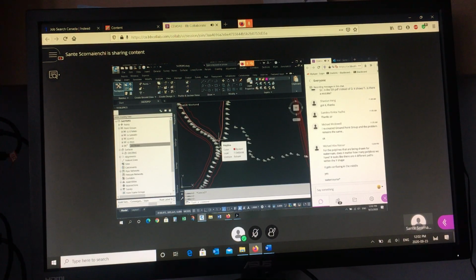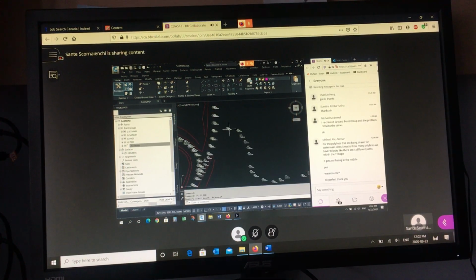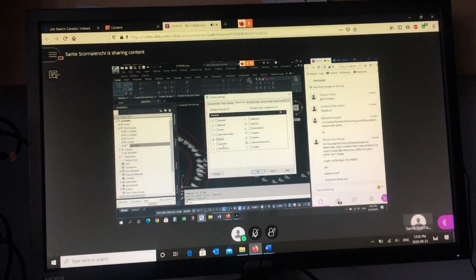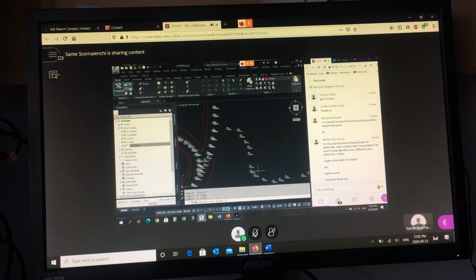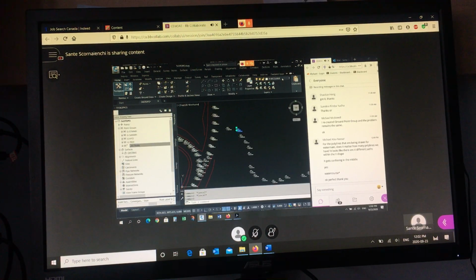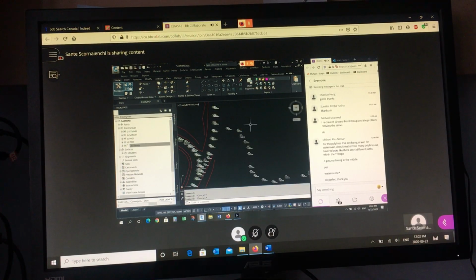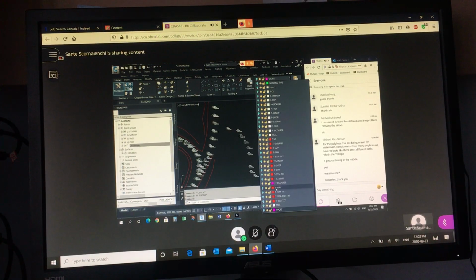Okay, so I can do this if I want, right? I can draw a polyline, connect the dot from up to my OSNAP node, polyline, and then just connect the dots. That layer's off, sorry. So I want to be in a layer called T watercourse. And then I draw, oops, not the point. I want the current layer to be T watercourse.